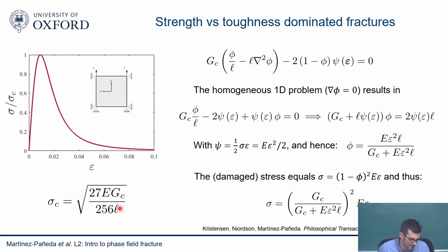Yes. So there's a bit of debate on that. It's a good point. People, for example, like Bazant, would argue that fracture mechanics doesn't hold that well in concrete unless you have very large samples, because they argue the fracture process zone has a lot of extensive micro cracking. There's a bit of debate on that. I'm not going to take sides. But in principle, you could have materials with very small fracture size, like in glass you don't see anything and then you see complete failure. Metals are a bit longer. In concrete, you may get a more spread distribution of the damage.